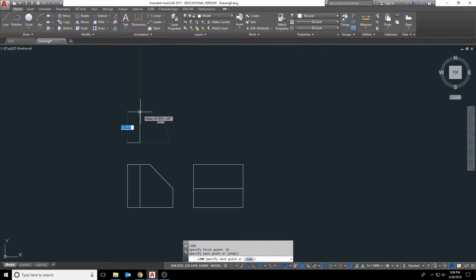So this is going to come up 42, which is just 60 minus 18. And then it's going to go back to this point, and then I can come up the additional 18 and then bring this across and then use tracking to just kind of fill in the rest of the shape, getting rid of this small segment right here.